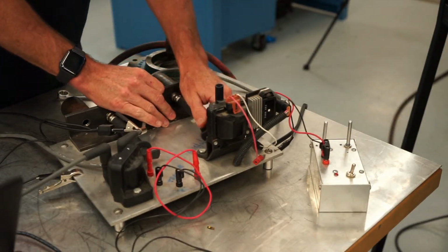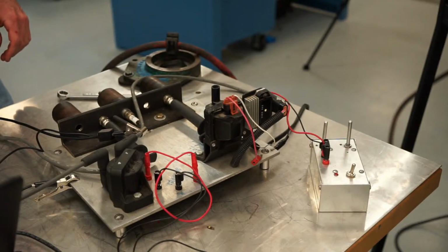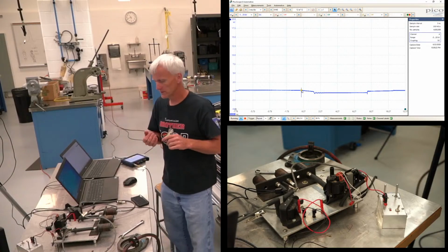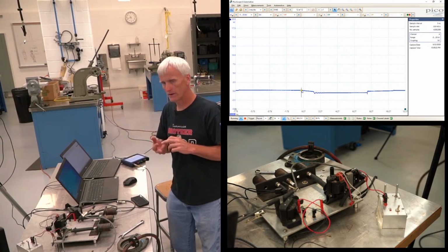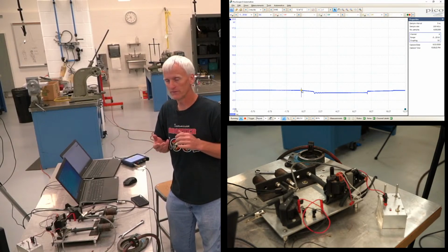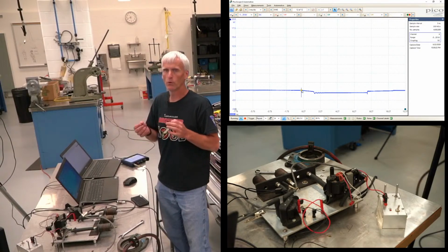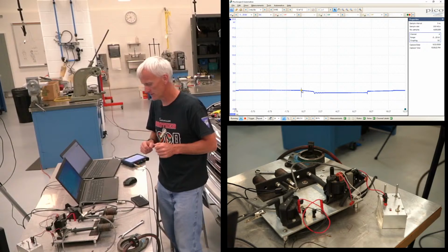A lot of students said it was air-fuel mixture, it was air gap, and those things do have minor effects. Air gap actually has a little bit more than just a minor effect, but the number one factor of kV is compression, and we're going to see that here in a second.